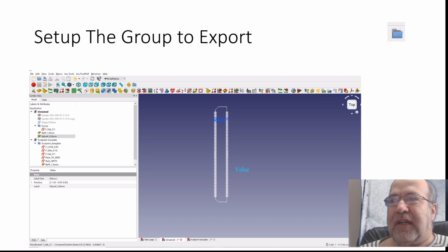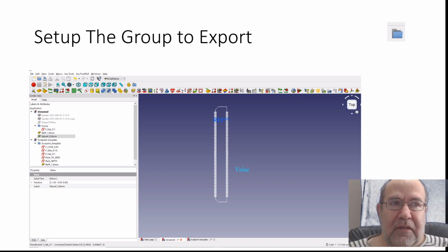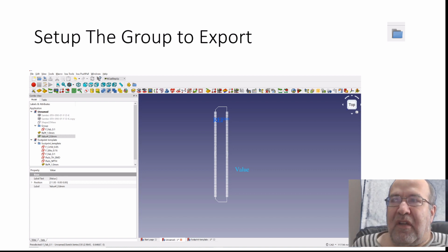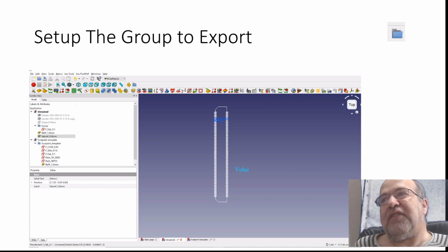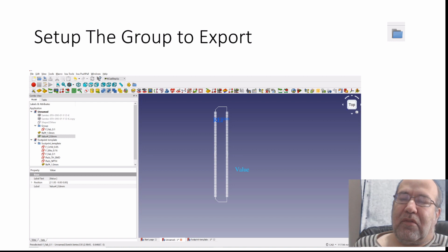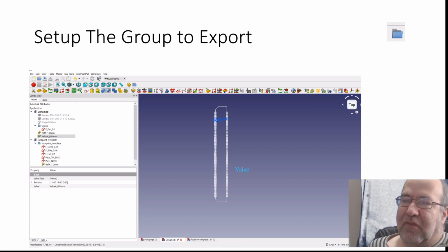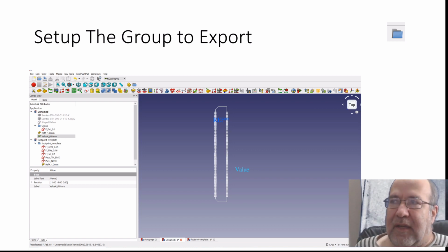If I wanted to create pad shapes and other things besides having a mechanical layer with all the details, I would need to copy the information into a different sketch and delete all non-relevant data so that the pads would be able to be created. I personally prefer to put my pads in Kicad and not place pads here.